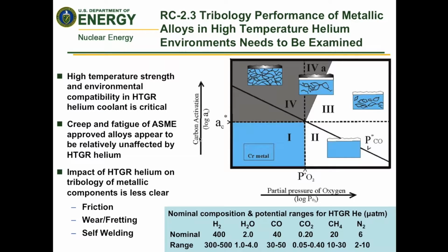Tribology, high temperature alloys, and helium. We've known for a long time that high temperature strength and environmental compatibility in the alloys for these high temperature gas-cooled reactor systems is critical. And the good news is we've done a lot of work on that and by and large found that creep and fatigue of the ASME approved alloys in helium is relatively unaffected by that helium compared to air. However, we are not at all as sure that the impact of the helium on tribology, particularly things like friction, wear and fretting, self-welding, is that we have an adequate basis for a regulatory position on that.